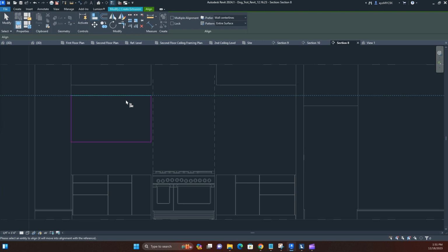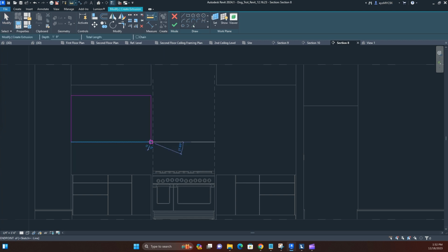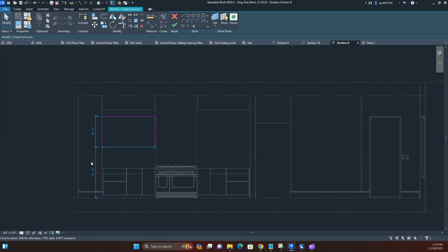So I need maybe 6 to 8 inches, and it stays 6 to 8 inches away from the soffit. I think I'm fine. Also another thing I want to point out, you want to make sure the distance from your wall cabinet to your base cabinet is within the standard, usually around 18 inches to 20 inches. So I took the measurement. I think that's fine.